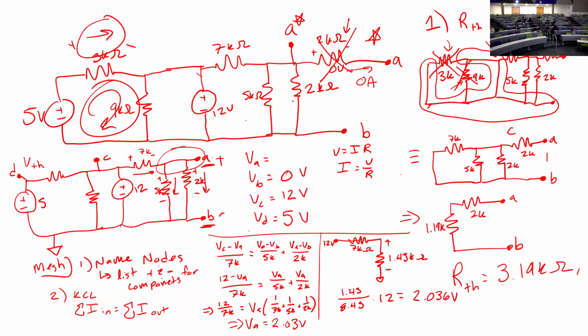Yeah, so this problem could get more complicated because if I say I have a capacitor at the end of it, I could then ask you, what is the voltage across the capacitor at t equals 4 seconds? Then you just solve for your time constant and plug into the generic first order ODE solution. But it can only get a little bit more complicated as we've learned so far. With the switch problems, it is not more complicated than this. It's just a little bit of a nuance off the get-go. You have to think about what your initial conditions are and how they switch. That's really the only thing to consider there.